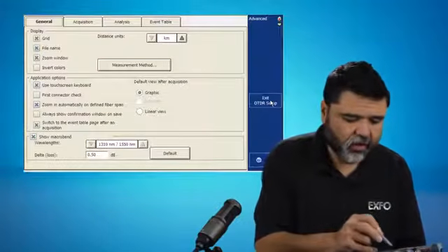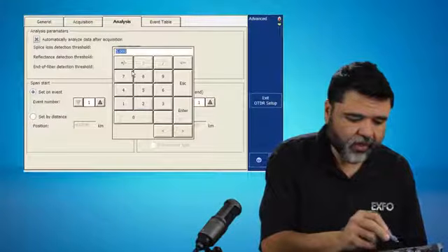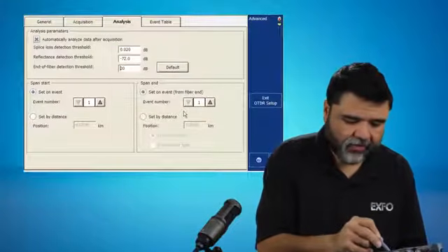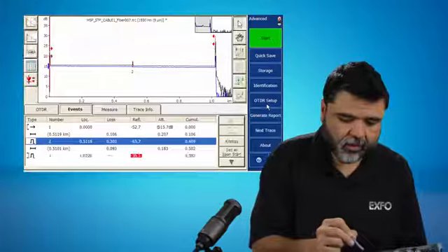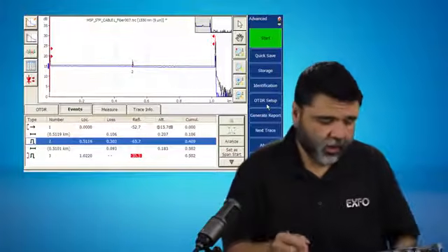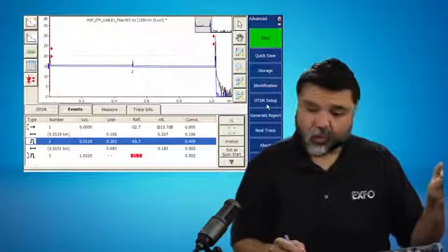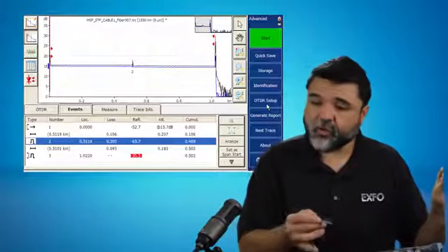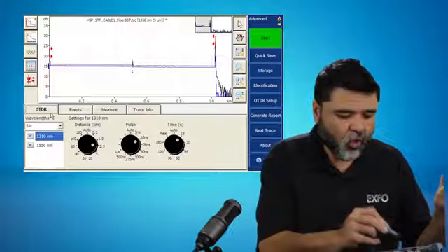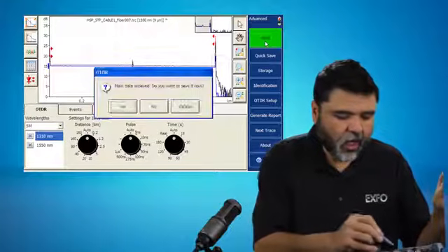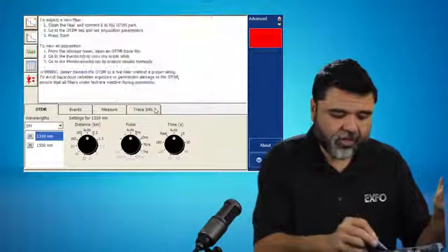So I'm going to go into the OTDR. I'm going to have it do something that it doesn't like to do. I'm going to have it look through a connector or look through a substantial event loss. So I'm going to go ahead and pinch the jumper at this location. And so that's that location, event number 2 on the display there. I'm going to go ahead and auto up again and then start a test.